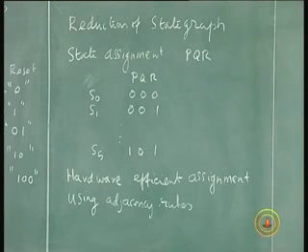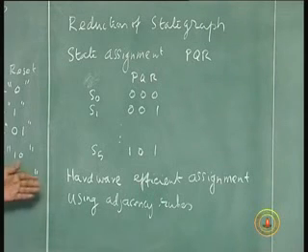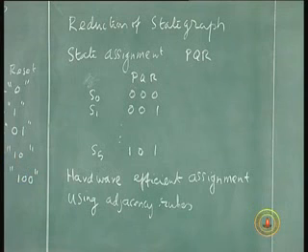When I have more don't care values, my hardware is simpler, you know that. When I have more don't care entries in my state table, my hardware is simpler. So to that extent it will also impact the hardware, but a more significant reduction is possible if you can even reduce the number of flip-flops. The same argument I can hold here. If you have a state assignment such that the transition always happens from one state to the next state which differs in only one variable, the switching activity or the transition is minimum, that is also efficient.